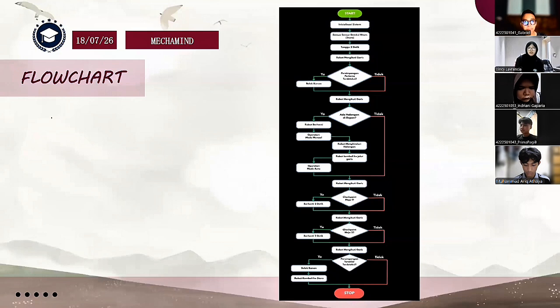If yes, then the robot will stop, and the operator will change the mode into manual mode, and then the operator will manually move the robot to avoid the obstacle, and then it will go back to the path of the line, and the operator will change the mode into auto mode, and it will continue following the line. If the robot doesn't detect any obstacle in front, then it will just continue following the line.